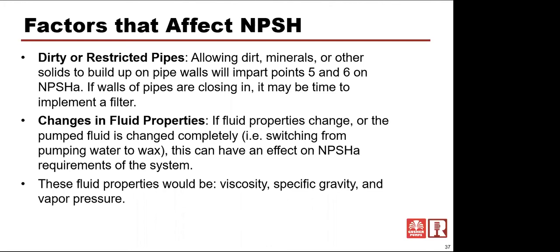Other concerns to NPSH would be perhaps viscosity. Viscosity affects how easily that flow goes through that pipe. So there are some other concerns, but in general, it's atmospheric pressure minus vapor pressure plus or minus the liquid level minus the friction loss. And that's going to get you darn close in most cases.